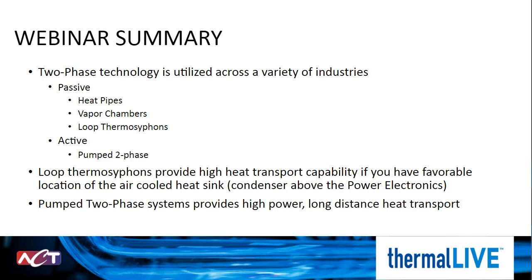In this webinar, we looked at several different types of advanced thermal management strategies and their application in a variety of markets. We identified heat pipes in the medical industry to isothermalize the row of sensors. The loop thermosyphon was used in the naval application to passively cool a high-power system. And pump two-phase was used in the data center industry to effectively cool a high heat density application in that small space claim. We also identified 3 potential strategies to cool batteries in an electric vehicle.